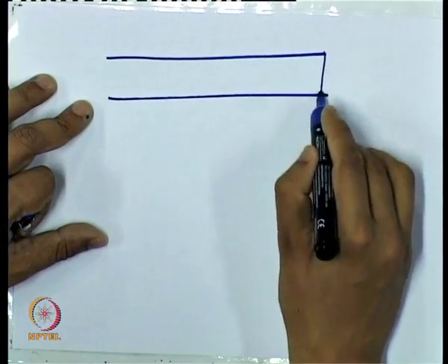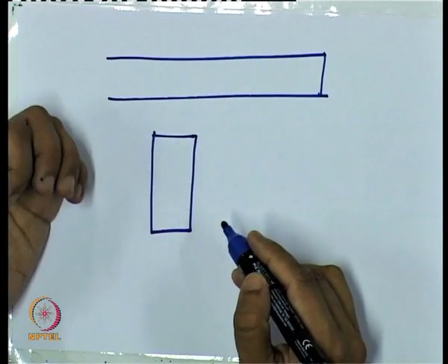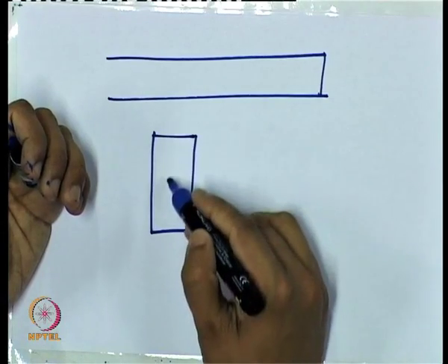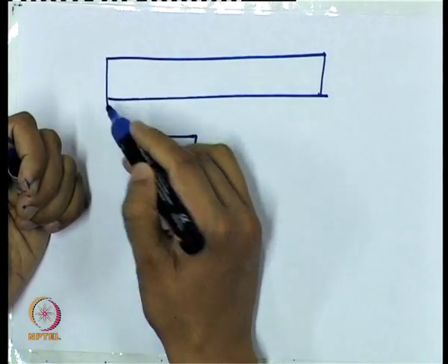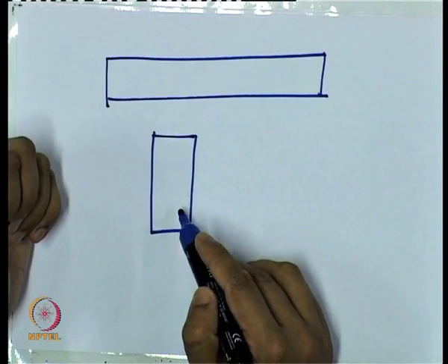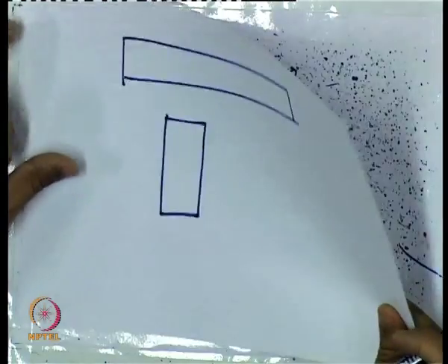So I said that both for the band pass and band stop filter, we would prefer shunt implementation of the resonator. So one way of realizing it is if we have our length tuned properly of this open stub, and say the resonant frequency is such that it corresponds to the high impedance state of this gap coupled resonator, then that is an implementation of a shunt resonator in shunt, and that way we can realize it. And as I said, series implementation of this open stub is not possible. However, one thing that might be possible is, without using an open stub, using a simple transmission line element.